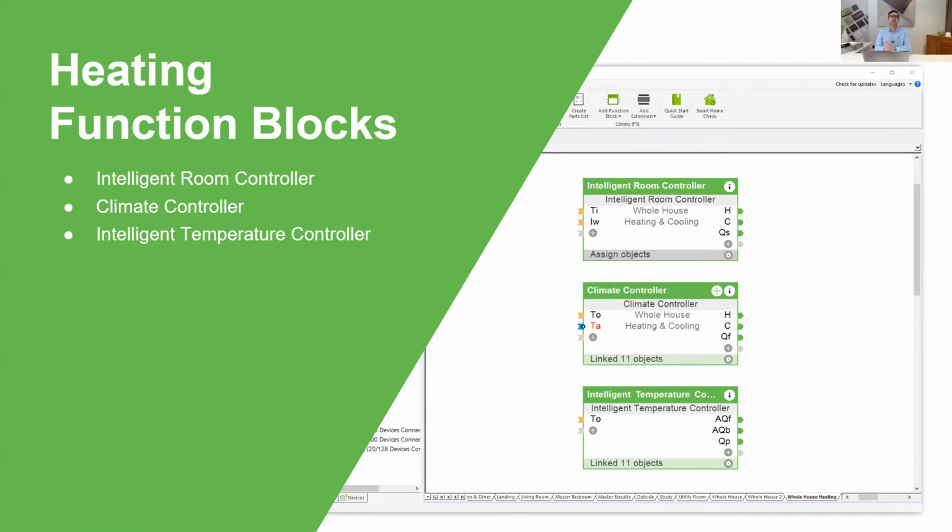A really, really important thing, though, that I need to mention about our heating control system: it's a zoned heating system. Zoned means all or nothing. So if you have a house and you decide to only put a valve actuator on 2 of the rooms, it will never work properly. You cannot partially zone a zoned heating system, all or nothing.